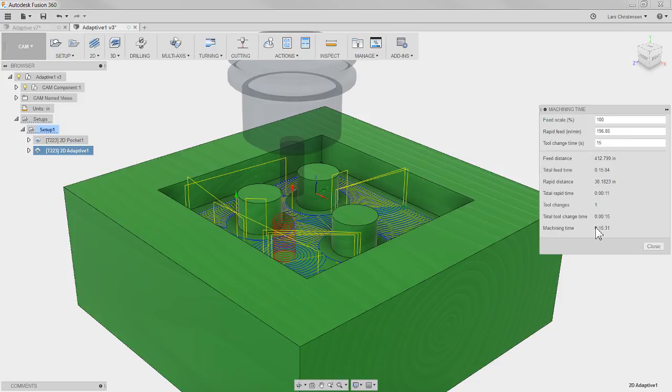This is why the sales guys for the CAM companies were saying, oh, this is a great roughing toolpath. Well, yes, it is a great roughing toolpath, but it's really just a smarter toolpath from start to end, because of the way it works, side milling out and never gouging the end mill.